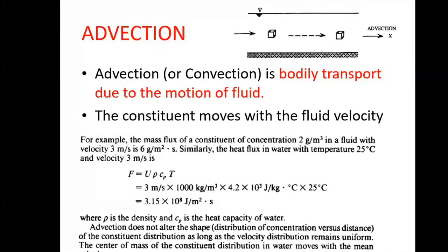So I need concentration in joules per meter cube. This is joules per kg. What will the answer be? Joules per kg. So convert it into joules per cubic meter of water. I have to multiply it with the density of water. So this rho Cp into T is converting temperature into concentration of the heat energy. Got it? This rho Cp into T is converting temperature into heat energy per unit volume of the water. That is the concentration of the heat.